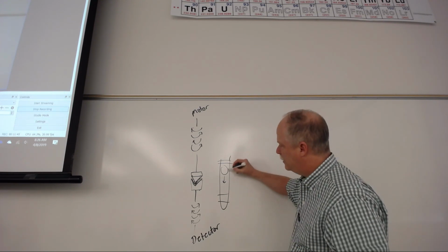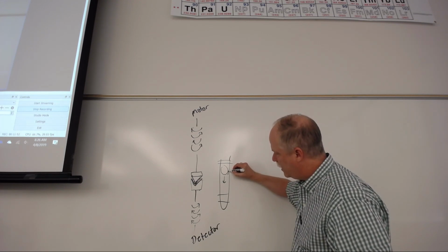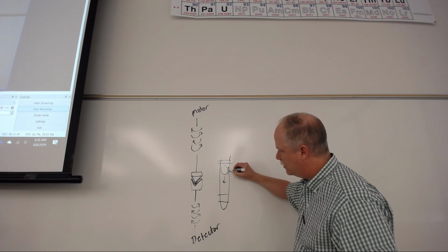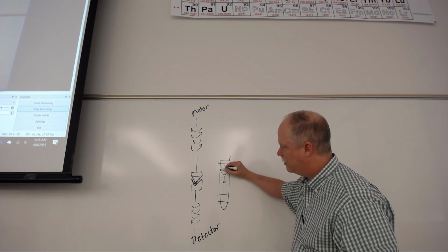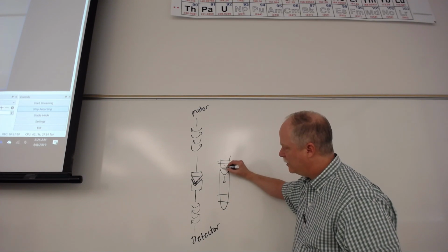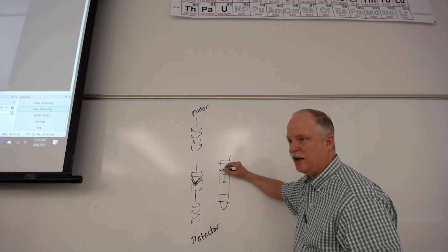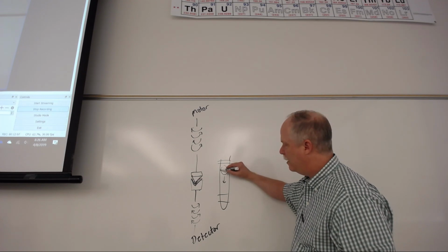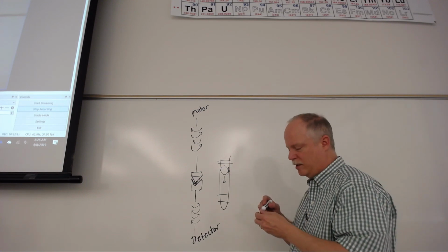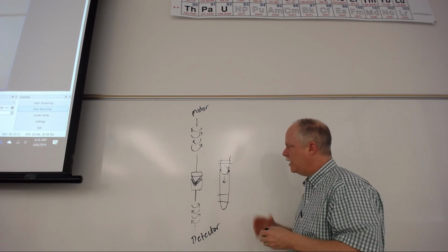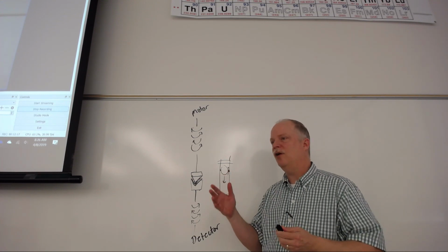Now this is going down, so the water has to squeeze, or the fluid has to squeeze through this defined little gap here on either side. And so that's a velocity gradient between this ball falling and the stable or still outside of the wall. And so that's proportional to viscosity. So it's another way to measure it. Now, surface roughness would just interfere with that laminar flow.